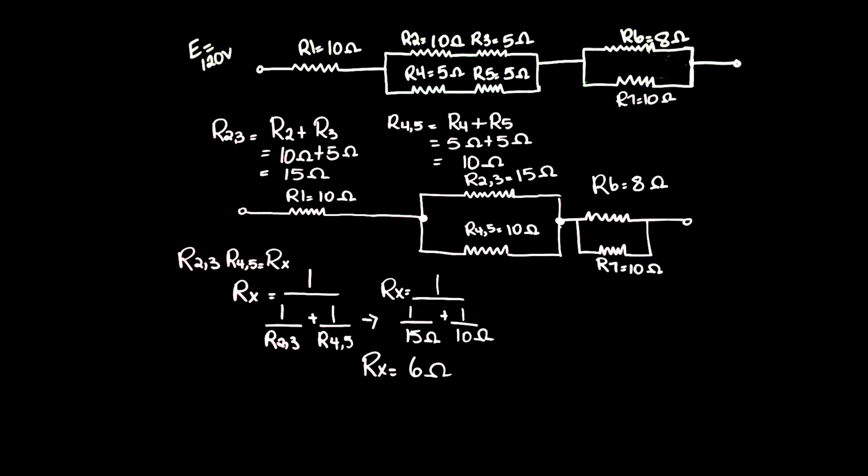And it's always true to say that the resistance total of a parallel branch will be smaller than any branch contained within the circuit. So R4,5 was 10 ohms. My resistance total for that particular branch is 6 ohms. So we have satisfied that rule. So I am going to now move into solving and reducing R6 and R7. So R6,7 equals, again, electrically this point is shared, this point is shared. So if you were to read the voltage value across resistor 6, it would equal the same value of voltage across resistor 7, concluding that this is in fact a directly parallel portion of this circuit.